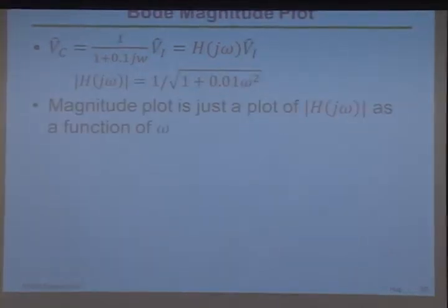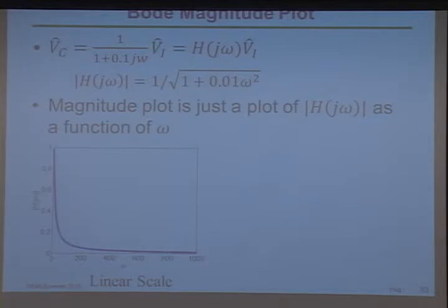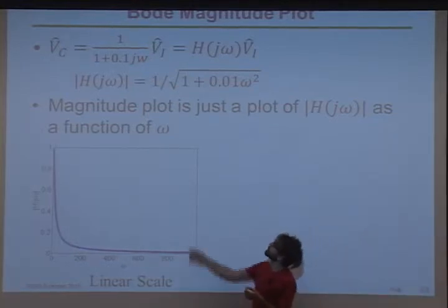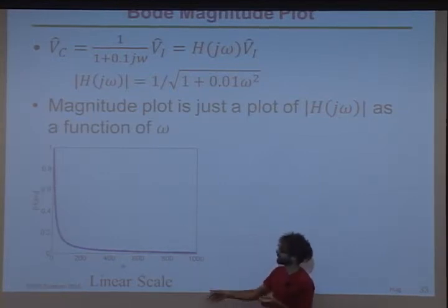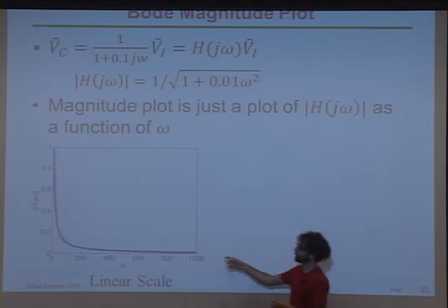Yes, this is a low-pass filter. So if you'd like, let's think about those two things separately. The magnitude made sense. Okay, so you could think of it this way: this is basically what I was saying as you tweak the frequency, how does it behave? The magnitude of your output signal, how much it tries to scale it, drops off as you increase the frequency. And on a linear scale, our plot looks like that.